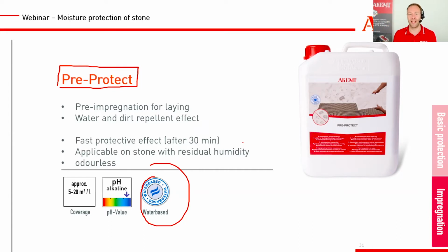That makes the cleaning of later used grout adhesive easier, especially when you are outside, where you usually have these rough flamed stones. Then it's easier for you to remove the residue of the grout, the cement films, the concrete films. And when you have protected all 6 sides, it's quite easy to clean it.